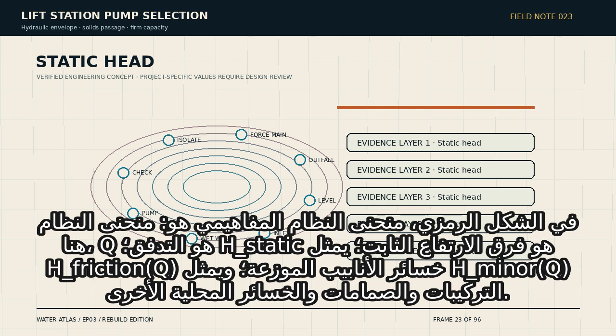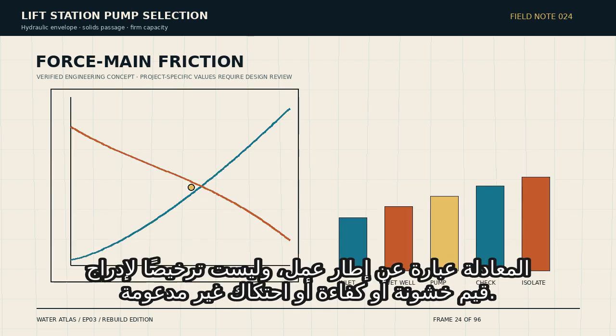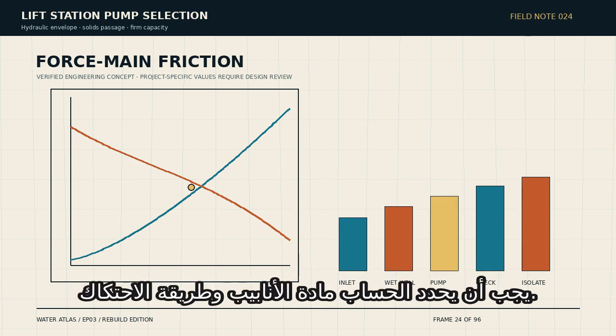The cited Texas rule specifically points to Hydraulic Institute standards for losses through pipes, valves, and fittings, and requires the friction coefficient used in head loss calculations to be identified and based on pipe material.